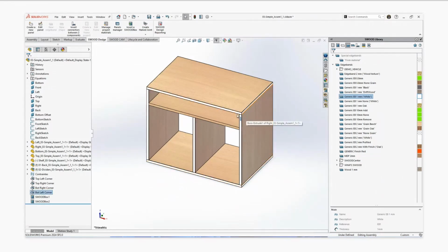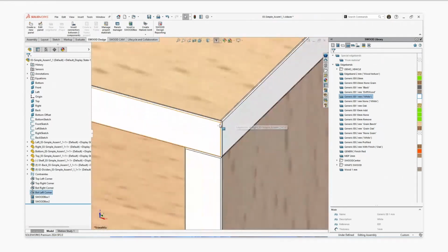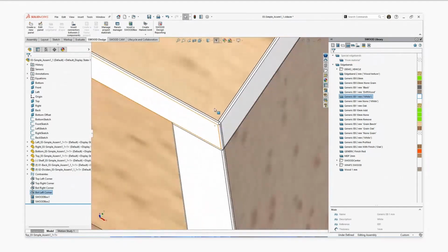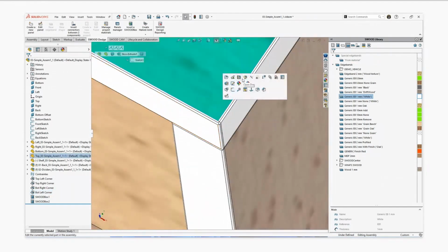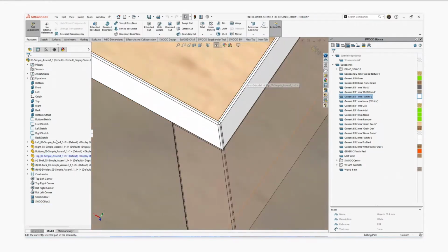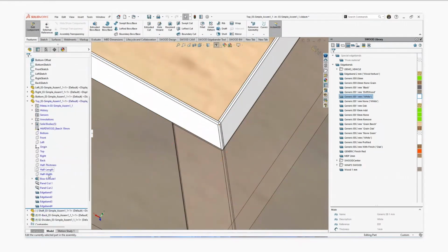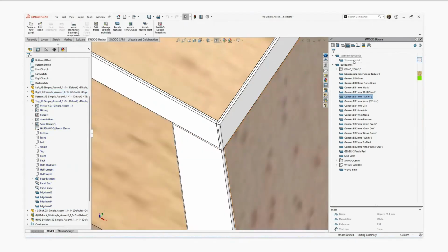And this edge band comes with some specific information about the shape and also some edge band order information. If I change the edge band order on the design tree, automatically it changes the edge band order on the 3D model. So you can go deeper and deeper in detail to put every piece of information you want. Okay, here just drag and drop, and I change everything from white here to a wood.